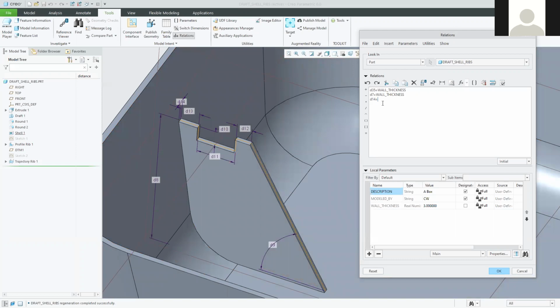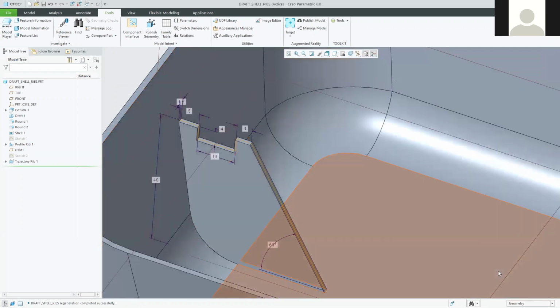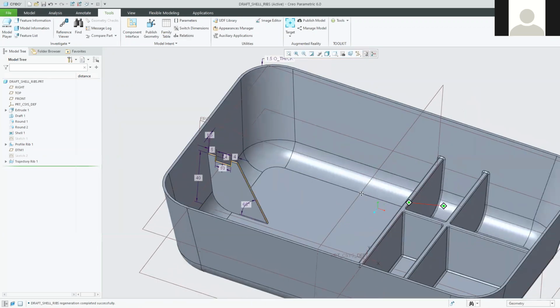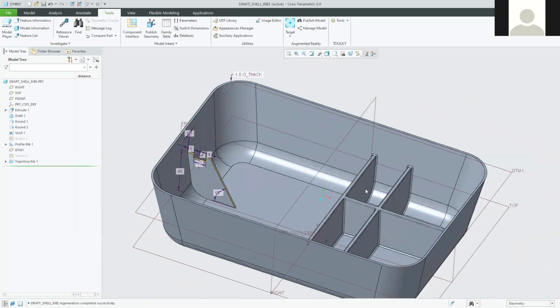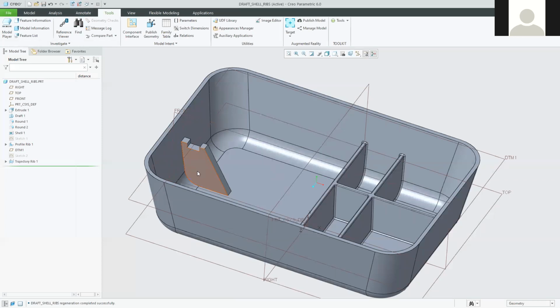And just to add a little bit more interest, what we're going to do with this one is insert wall thickness, but let's hope this works. So I just did a copy and paste there. Let's do wall thickness multiplied by 2. So I've just used the asterisk key and put a 2 at the end. Let's click on OK there, and then we can do a rebuild on our model and see if it actually does what we think it's going to do. So rebuild, yes, it seems to do that.